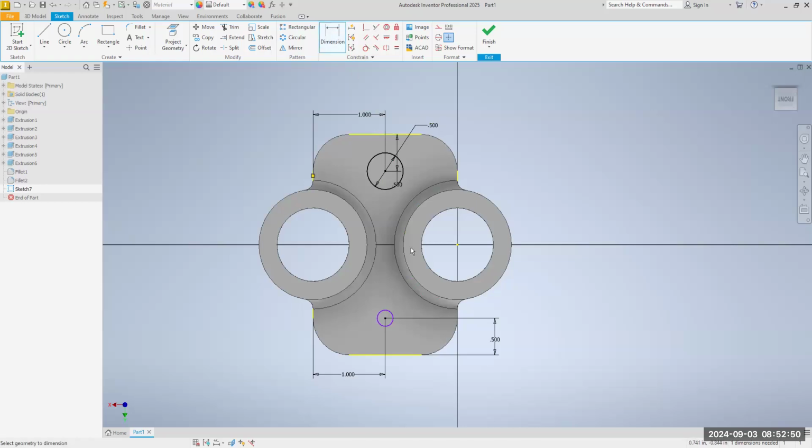We got to change the diameter now. And of course, notice I'm clicking. Watch this. I'm going to undo that. Here's the undo button up here in case you make a mistake. Hit this little white arrow, back arrow. I'm going to go to the dimension tool again. Click, click. And after you click the second time, that's when the dimension comes up. We're going to make this 0.5 and click on the green check mark.